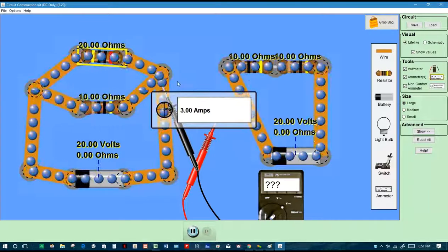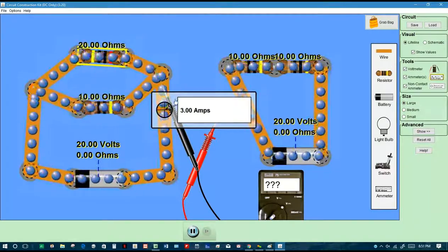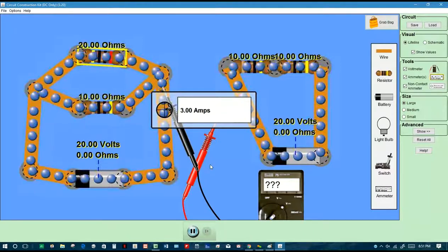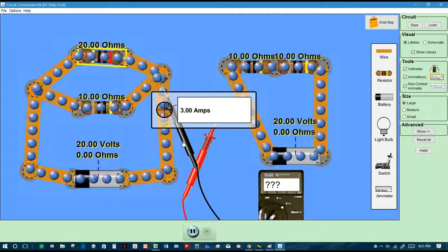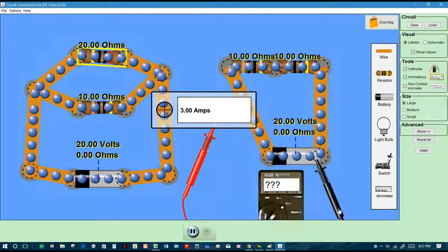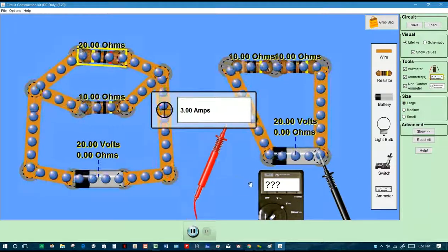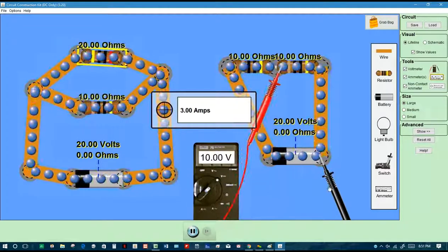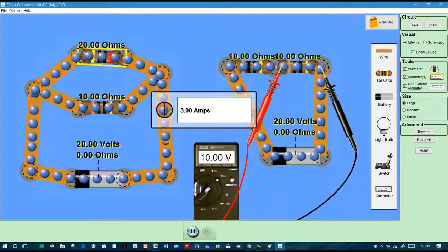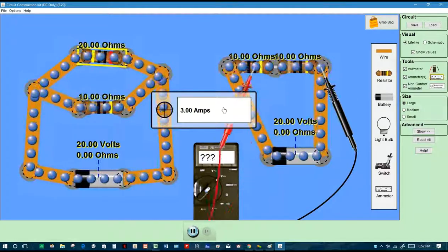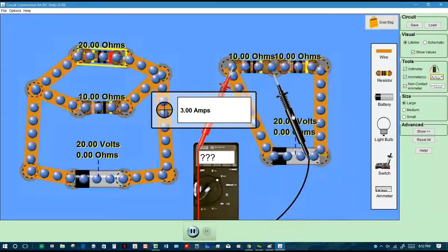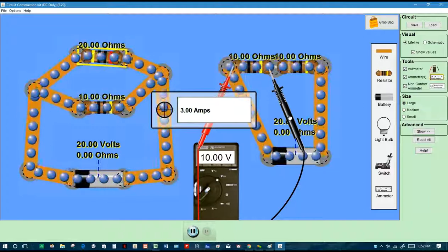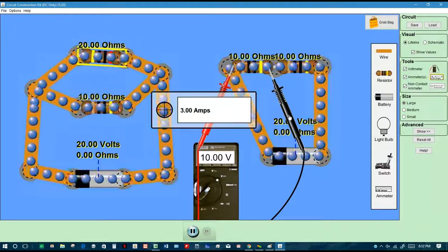And so the important thing that I want to leave you on, because I only got about 8 minutes left, is the best part of a parallel circuit is that the voltage doesn't divide up. Remember, if we go back over on the left to our series circuit, the voltage on this battery was 20 volts. And then how much was it using to get through this first resistor? 10 of those 20 volts was being used to get through that bit. How much was being used to get through the next resistor? Another 10, remember that? So we had a 20 volt battery, but only 10 volts was being used on one resistor, 10 volts was being used on the other resistor.